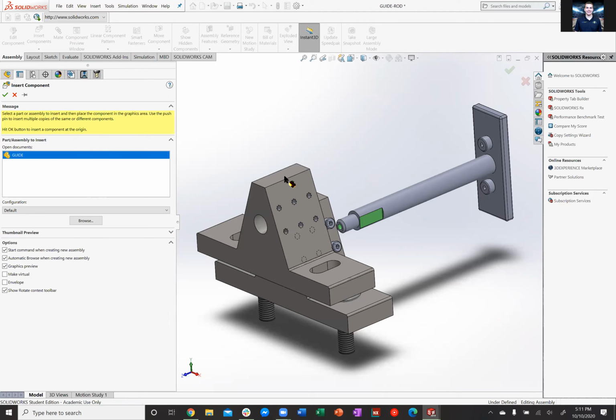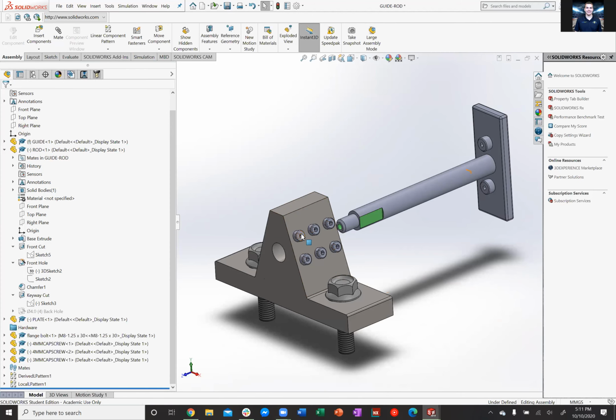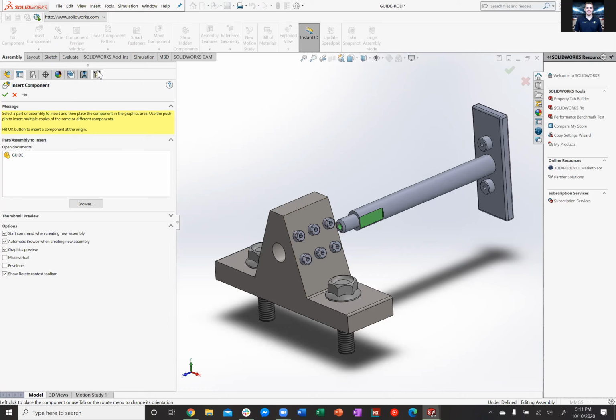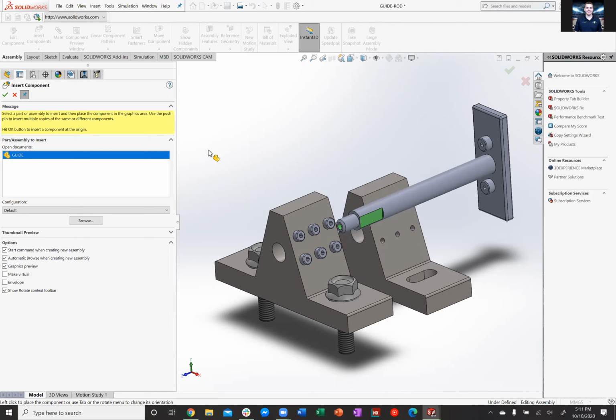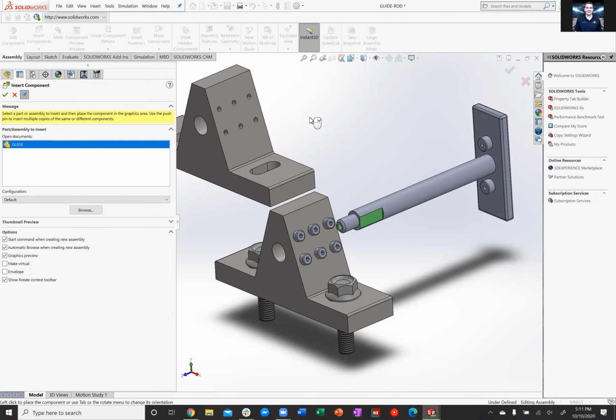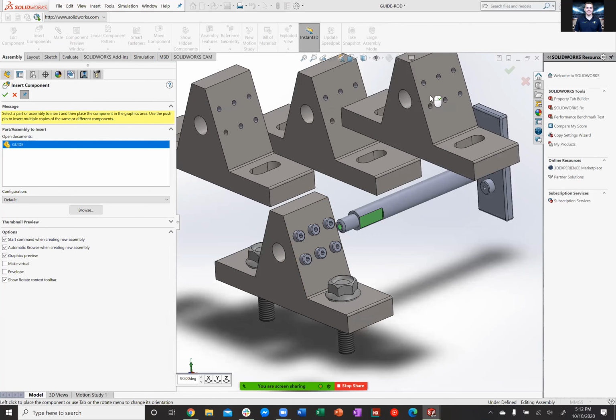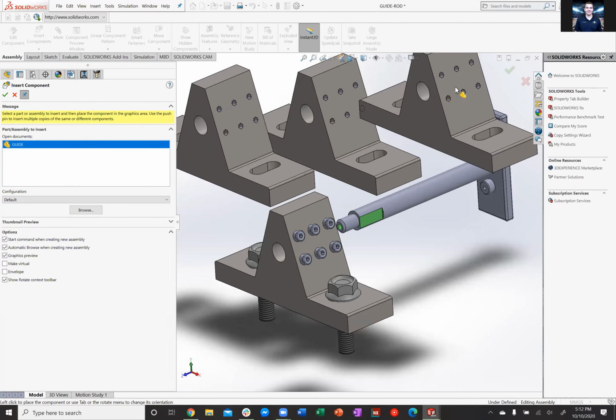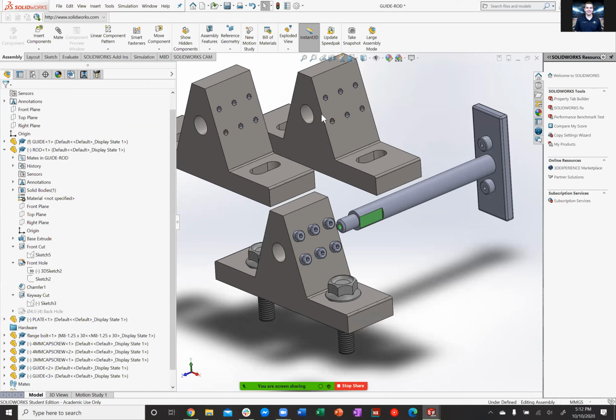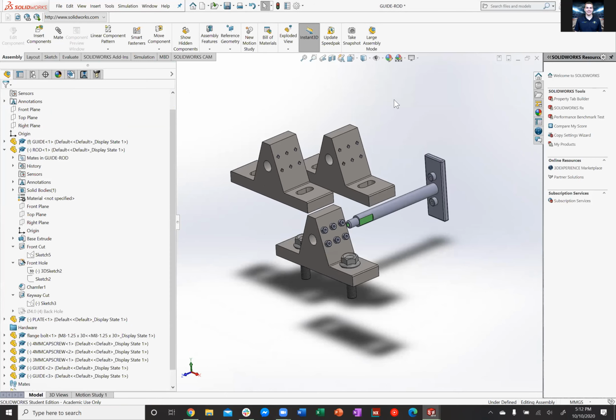For screws, for example, if you are designing a part and you want to put all the screws in CAD, and you don't want to keep clicking insert, click on it, put it in here, and then this disappears. This little pin right here will keep it so that you can keep adding parts until you have as many as you need. And then you click the green arrow or escape, and it'll stop inserting parts.